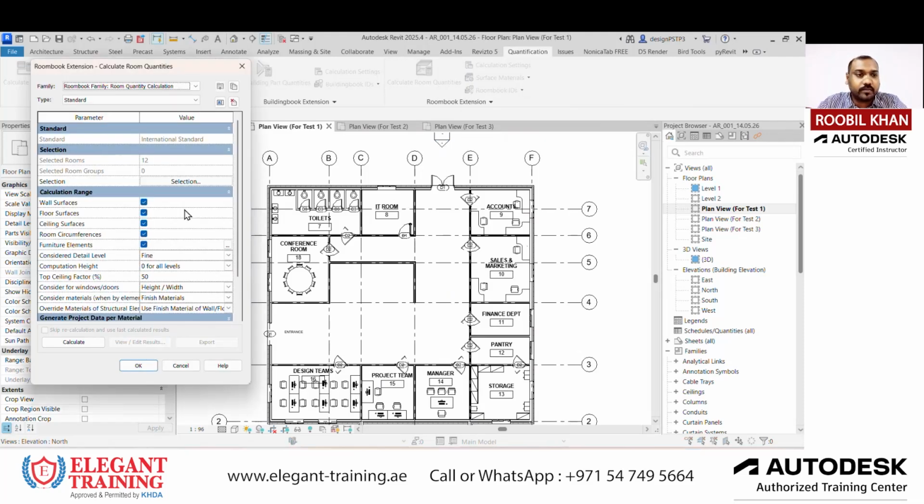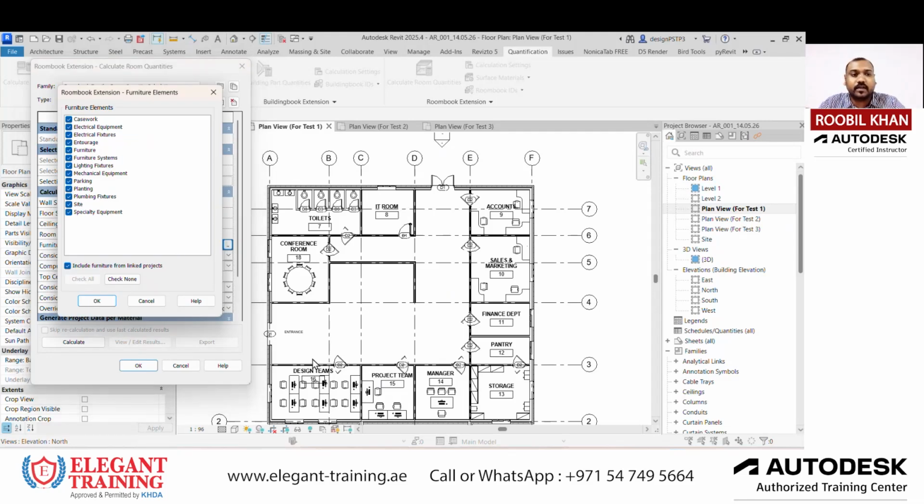Once you open Calculate Room Quantities, from here you can select wall finishes or whatever things you need. You can select the ceiling surfaces, floor surfaces, and even the furniture elements, so you will get a quantity of these furniture elements also. For example, here I'm just avoiding the ceiling surfaces and the room circumferences, so I include the wall surfaces and floor surfaces. Also, if I click on the three dots on the furniture elements, here I can select the categories which I need to include in the quantity. If I need the furniture or the plumbing fixtures, I already have some plumbing fixtures over here, so I can include that.